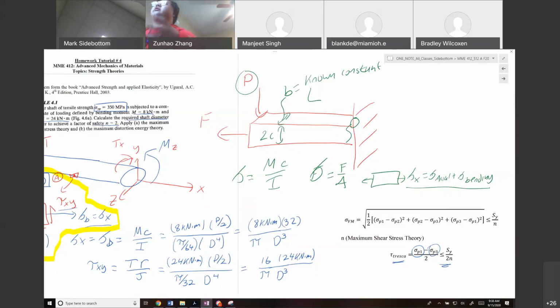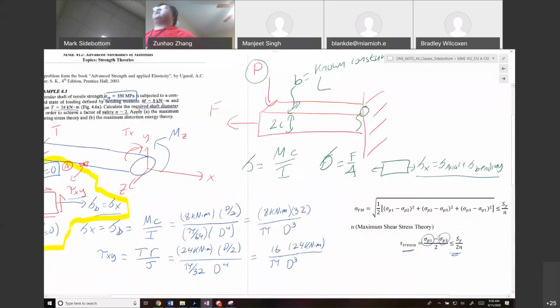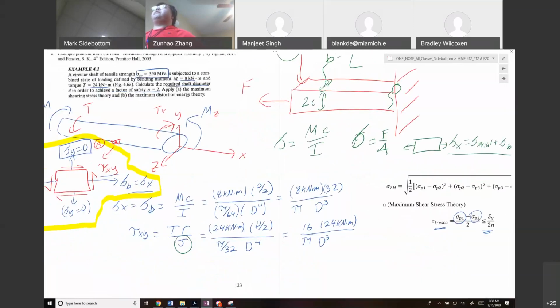Yeah, but in your original question, the rod is rotating, the square bar is not rotating. Yeah, so you would need to use the polar moment of inertia for a square bar. Which I'm pretty sure the polar moment of inertia is equal to Ix plus Iy. Right? And then you'd have to use R, the distance from the centroid to the maximum point on the beam.